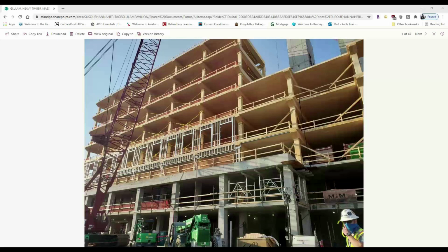What we found though is it really doesn't matter too much if the wood gets wet. What really matters, however, is how that wood is dried out. And we're seeing plans where once a building is closed up, applying heat in a very controlled, slow manner, along with humidifiers to keep the relative humidity at a certain percentage, and draw down that relative humidity as the temperature is raised over the period of maybe a week or two or longer.